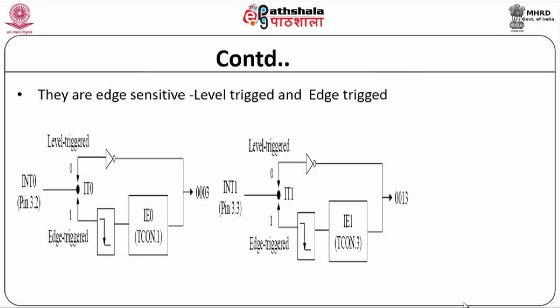Both are nothing but an input provided from outside, based on which the system has to work. If I provide a 0, then with level triggered it gets interrupted. If it is 1, it does not. But remember that when I am getting a square wave, at any time of the flat portion of 0 it gets triggered, but I need to fire at only one instant, where it goes from 1 to 0.